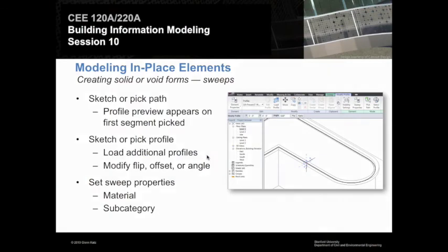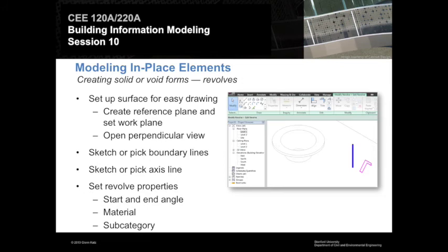Okay, Revolve looks like this. Okay, you got a profile and you basically have an axis. You're going to rotate that around. Okay, so not too bad. Now for my snowman, let's think about this. If I draw my axis down on the ground or my profile on the ground and we rotate him, he's going to be lying on the ground. Okay, so what I probably want to do is actually have something called a reference plane or a work plane where I can sketch vertically as opposed to down flat on the ground.